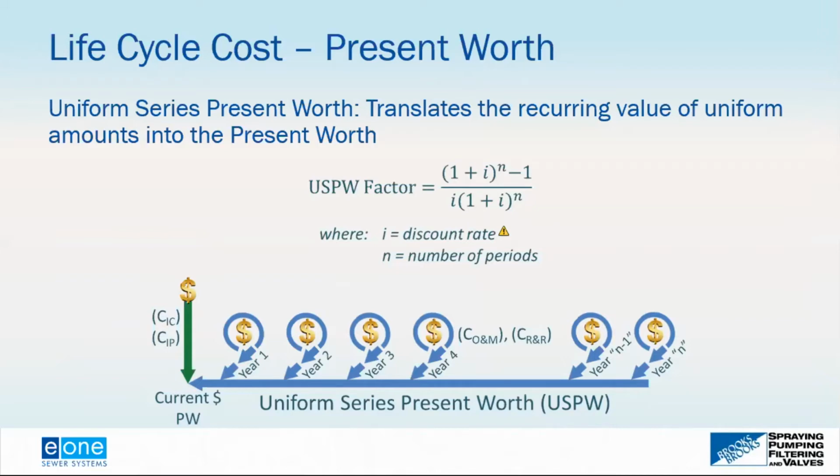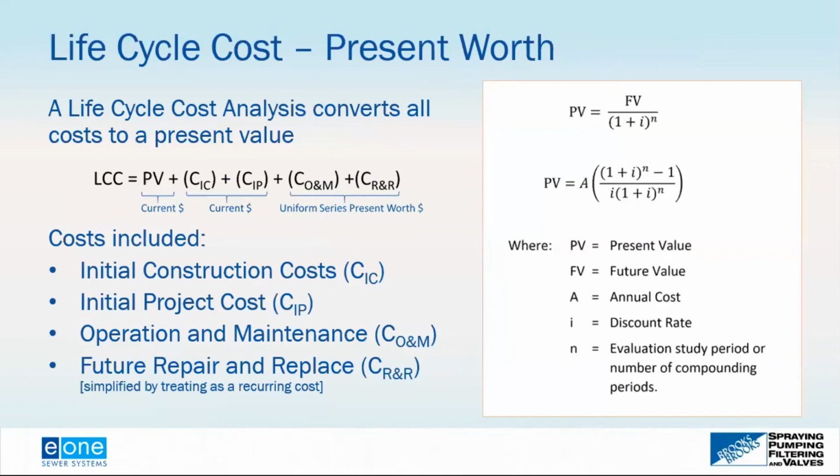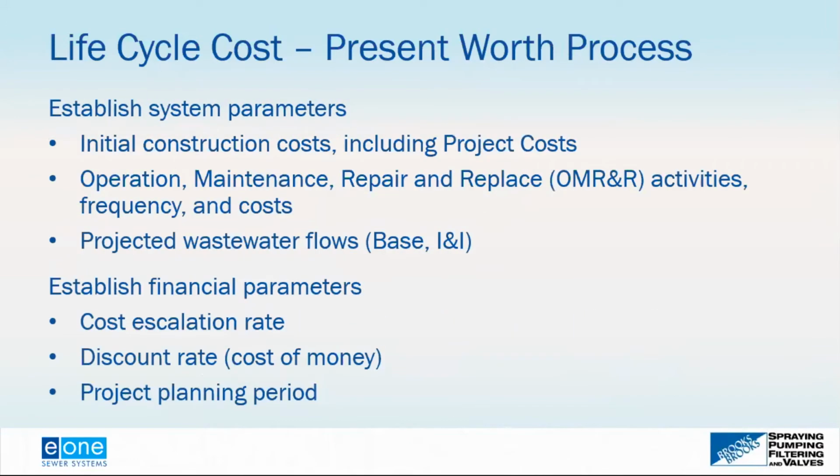So you just use standard economic equations. In this case, it's the uniform series present worth. We assume that the cost to maintain a pump or the cost to maintain a sewer system will be the same every year, and the discount rate adjusts for inflation. So you would bring that forward into a present year value, sum it all up into a present year value. So it's not that difficult to do. And as I say, the formulas that we have here, these are our standard economic formulas. So it's nothing really unique about doing a life cycle cost analysis for a wastewater collection system evaluation.